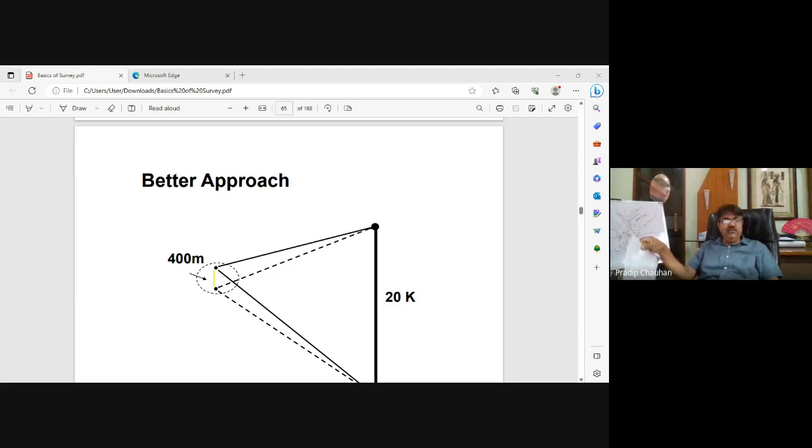Another approximate term is a bigha. If you see bigha in Gujarat, you will find 25,600 square feet equal to 1 bigha. If you go to Bihar, it reduces to 18,000 square feet per bigha. So bigha is not an appropriate term. Acre is the appropriate term in square feet: about 43,560 square feet, or 0.4 hectare. 40% of a hectare is an acre, and in Gujarat, 25% of a hectare is a bigha. So these are all the dimensions to measure area.